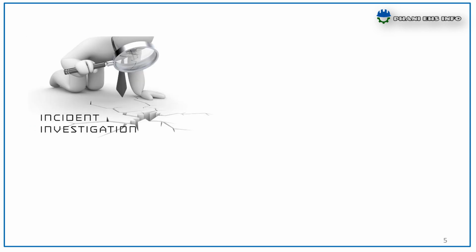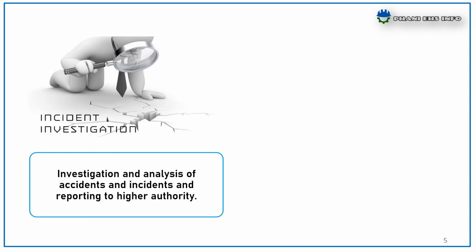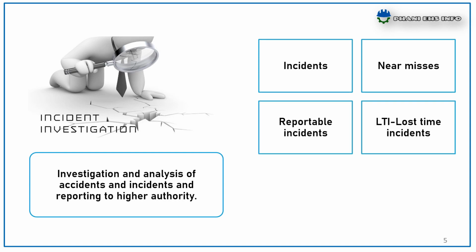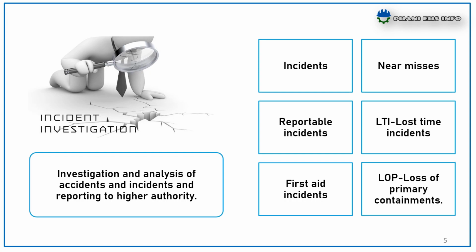Investigation and analysis of accidents and incidents and reporting to higher authority, which means we have to follow up the incidents, near misses, reportable incidents, lost time incidents, first aid incidents, and LOPCs, which means loss of primary containment.